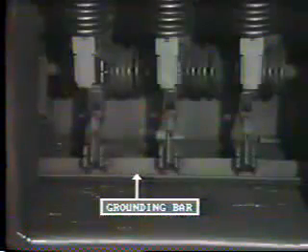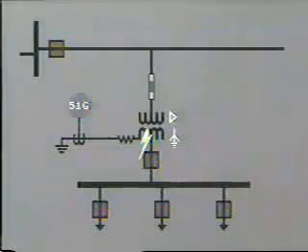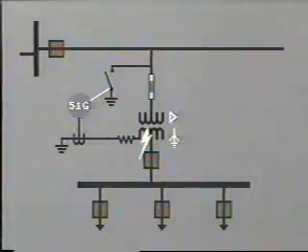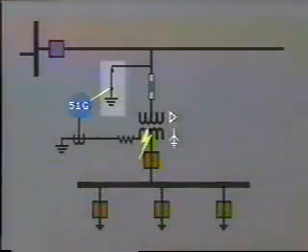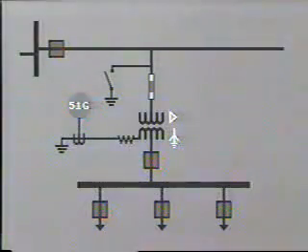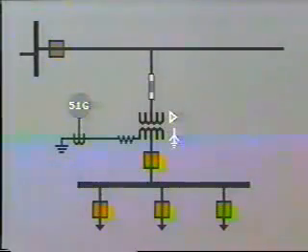One method of initiating the trip is to have the protection relay trigger a spring-loaded ground switch. This will apply a solid ground to one of the lines on the high-voltage side. This in turn causes operation of the ground relays in the remote station and so opens the breaker. Depending on system design, the ground switch could be three-phase or single-phase.